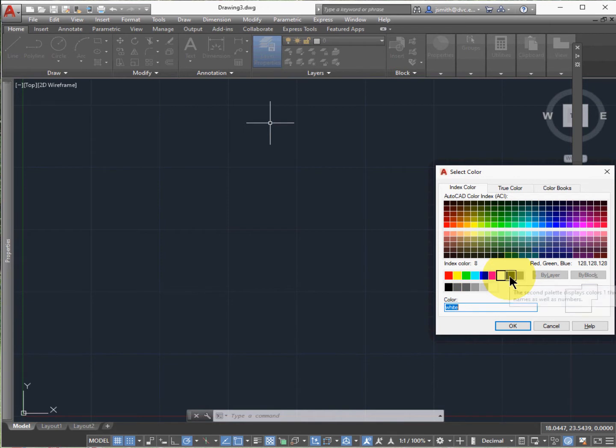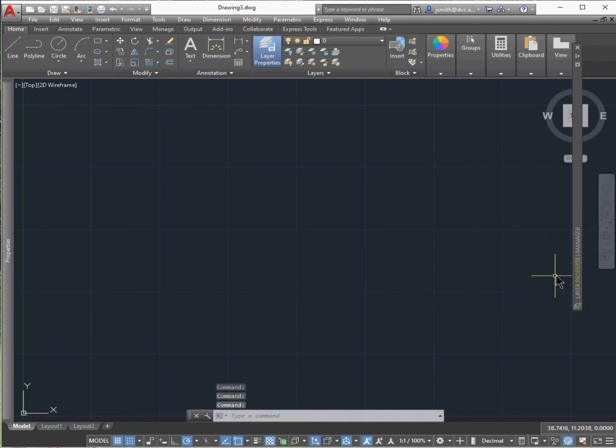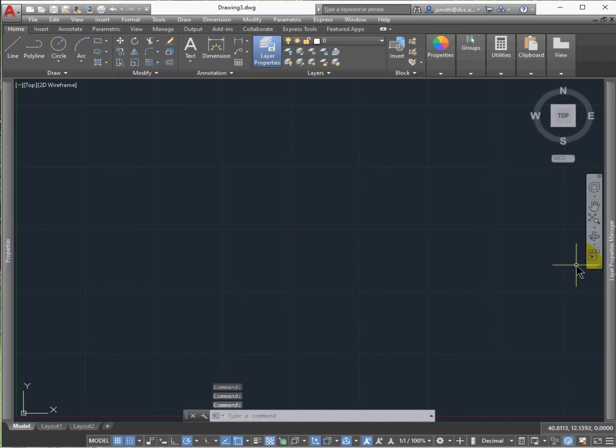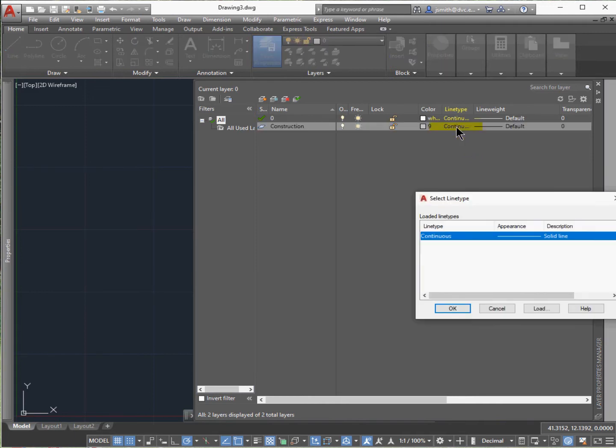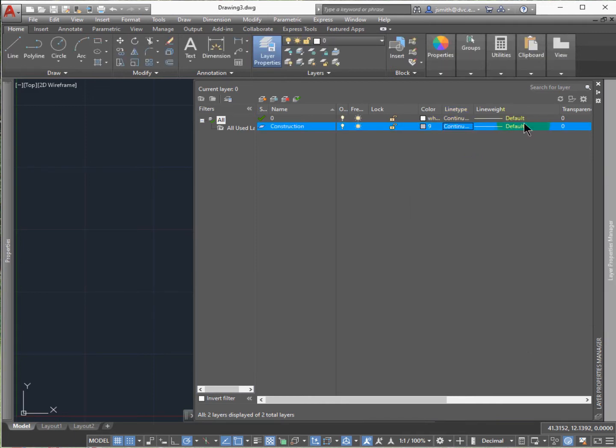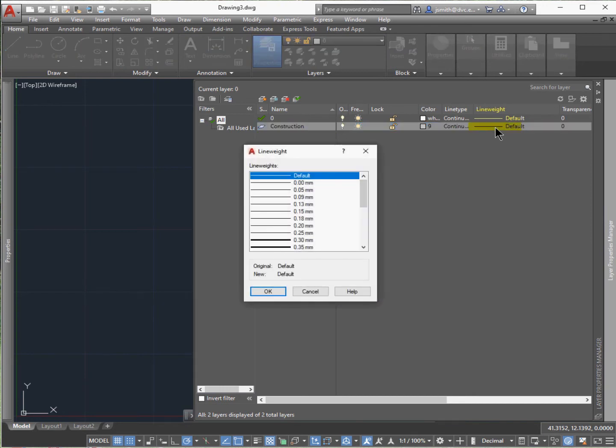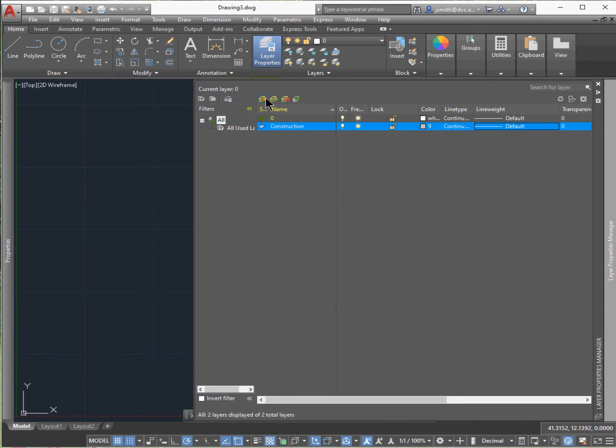And this is very typical for when you're doing drafting type projects where you certainly don't want to have all the layers being shown. This is unusual in this chapter because you are being required to show your construction lines, and so you want to make sure that layer is on. And the construction line is going to be gray, which is kind of grayed out, continuous. And then we're going to make another layer, and we're going to put the object lines.